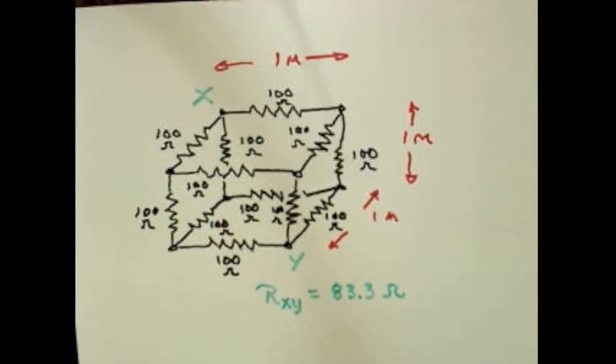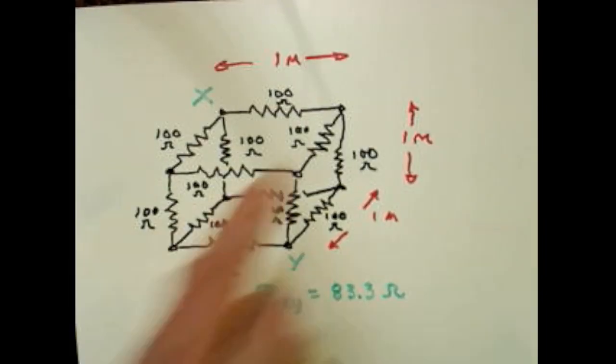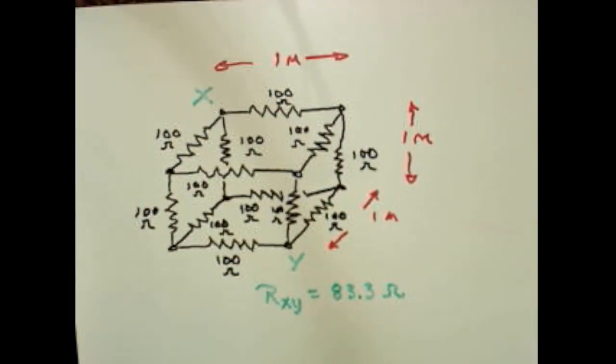And in a ballpark, given that the 100 ohms is a very shaky number to begin with, it depends very much on soil type, and that soil type is something that escapes laboratory measurement, in the sense of you being able to go out in your backyard and, well, you could directly measure it, that's for sure. However, Earth is not homogeneous, and it's not always 100 ohms everywhere, even if in aggregate it's an average of 100 ohms. So we're going to discard all those complications and just go with this as you see it.